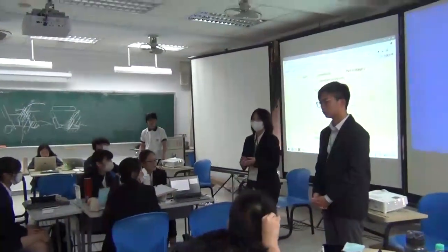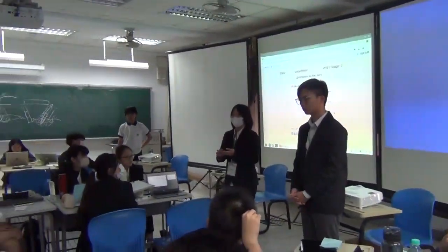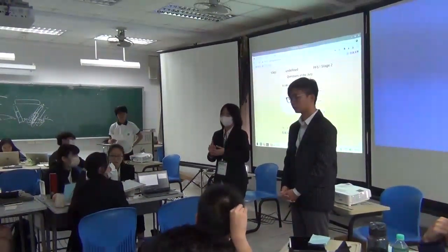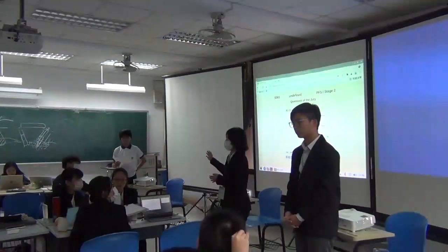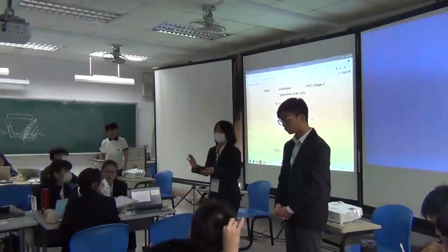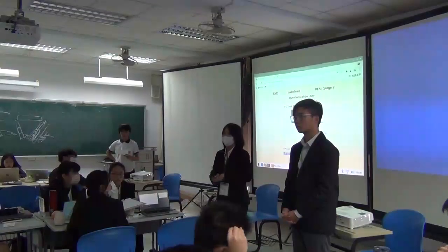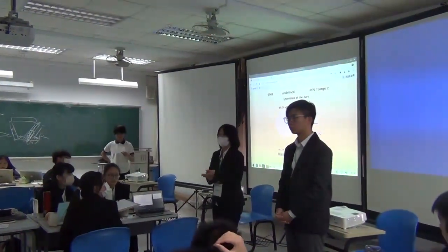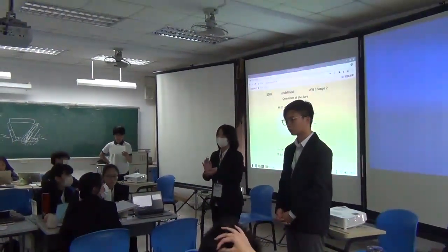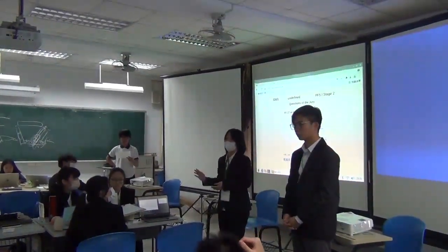Okay, how about the reviewer? I think they use the centrifugal force because that is equal to m r omega squared. So it means when the rotating speed increases, the pumping speed will also increase. And I think that is related. It sticks to their experimental results. But they put in Bernoulli's principle, and I think that can only be used in the ideal situation. If they want to use that, they need to consider the viscosity of the water or the friction of the water. So I think that cannot be used in this experiment.